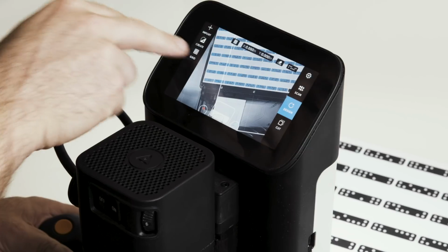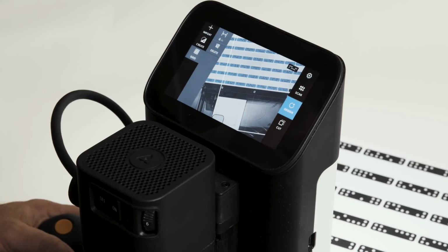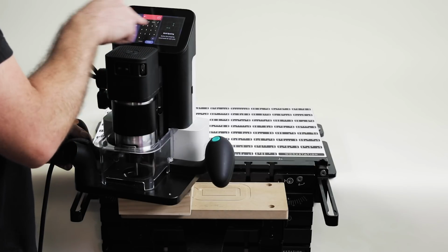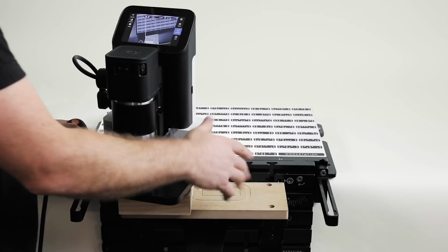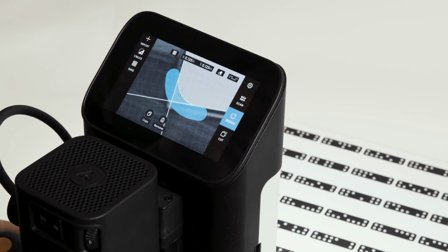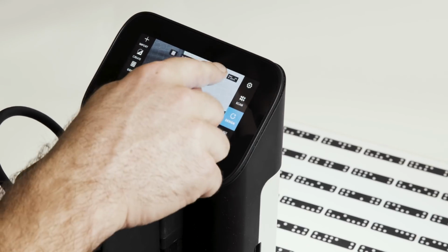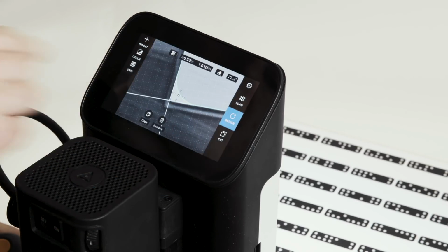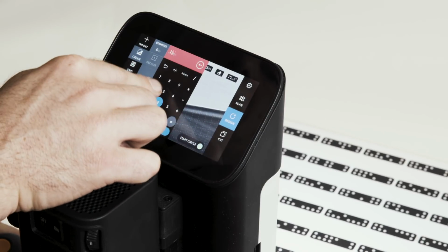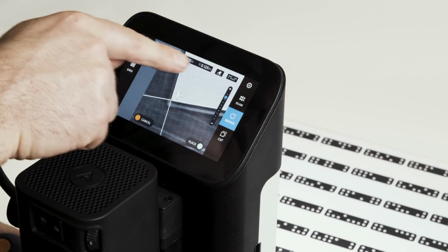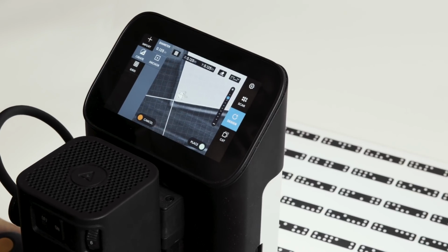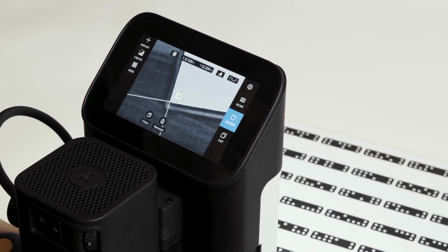And then the opposite is also true. Grid modify. Once again, we don't have to reprobe or anything. We're just reusing that initial probing information and going in and changing the increment here. So I'm modifying this down to 0.125, and we'll zoom in again. So you'll see here, I'll erase my cuts and erase this old object, and I'll create a circle that's 0.125, and I'll place it at exactly 1/8 of an inch in from that corner. So you can see here how I'm jumping in 1/8 inch increments, and the anchor point is centered.